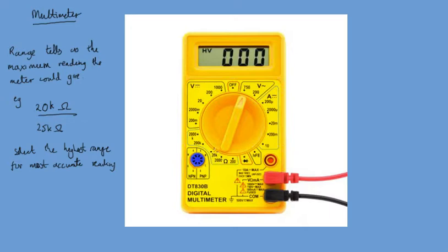It might not appear on the display. So you go to the highest possible range that you can to read. Generally you would start at the highest and then work your way down. The exception to that rule would be in the direct current reading. But we're going to go through the specifics for voltage, current and resistance in a minute, so we'll explain that in more detail then.